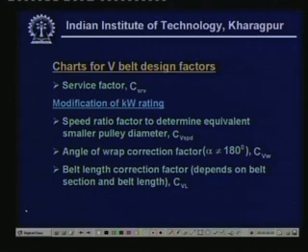The subscript SRV denotes service. The service factor for the V-belt and the flat belt are identical. There is almost no change between the service factors you will utilize for a flat belt or for a V-belt. It is typically dependent on the type of drive, environment and number of hours of operation, etc., as we have discussed for the flat belt.